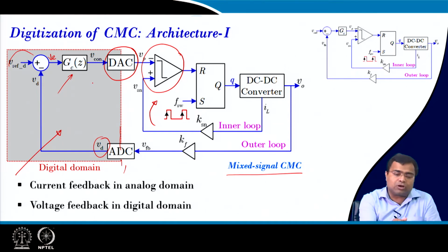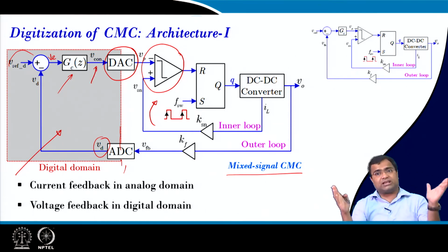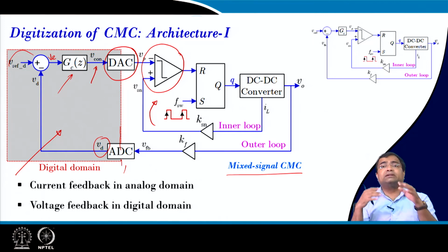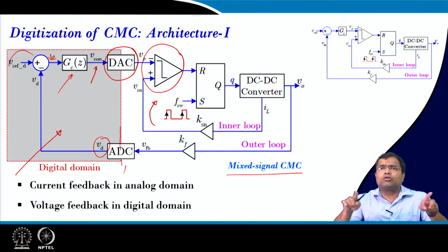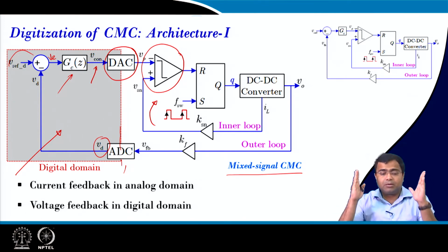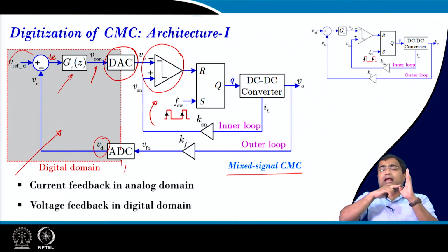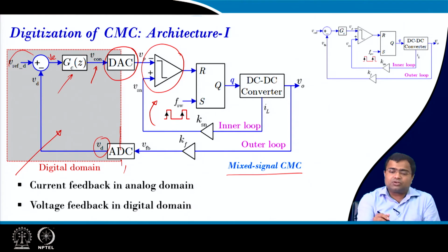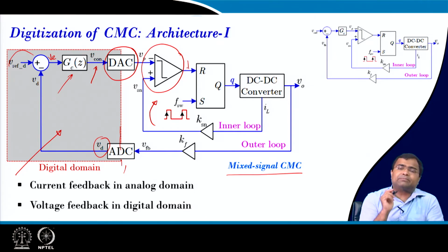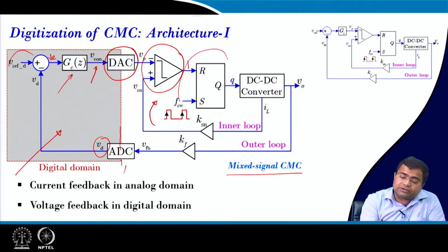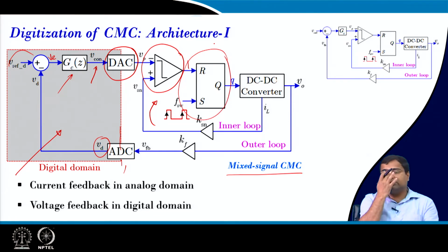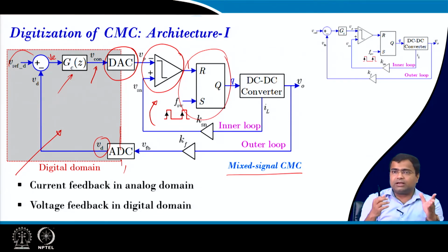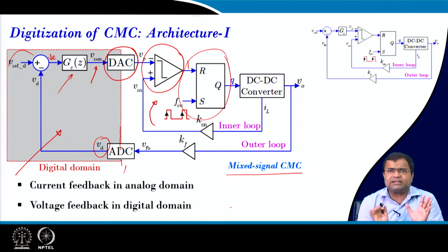So, the controller output will also be constant for the whole cycle. Now, the DAC output will also be more or less constant for the cycle, but the inductor current, when it touches it, that means in peak current mode control, there can be a spike. So, you need to use the trailing edge modulator that will avoid any fast multiple switching. So, there is a modulator, and this is pretty standard.